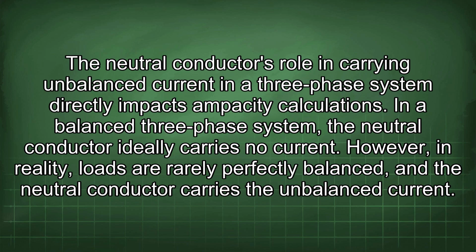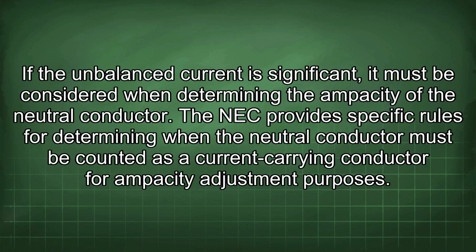In a balanced three-phase system, the neutral conductor ideally carries no current. However, in reality, loads are rarely perfectly balanced, and the neutral conductor carries the unbalanced current. If the unbalanced current is significant, it must be considered when determining the ampacity of the neutral conductor.